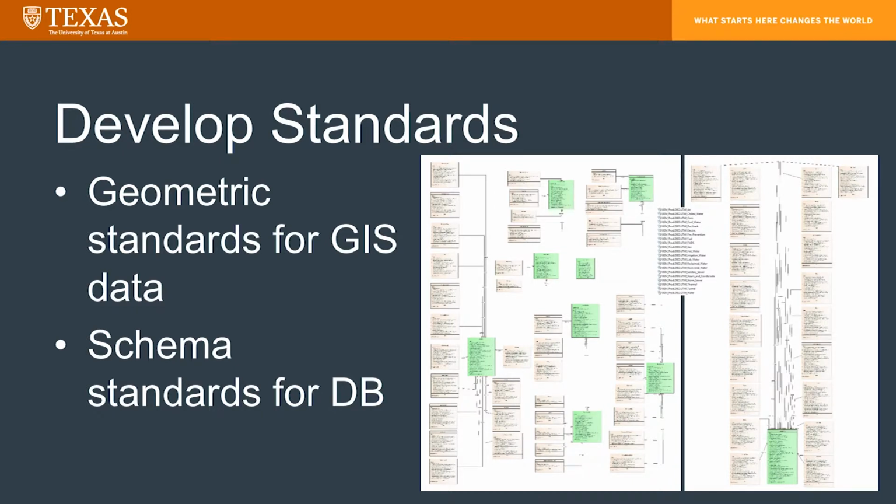Are your polylines going to break on nodes? And what I mean by nodes, those are going to be like gate valves and manholes and junction boxes, different things like that. Are your polylines going to break on those objects, or are they just going to be continuous through them? Are they going to break at intersections? These are types of things that you're going to be able to clean up as you're going through and separating out all this data, because that is what it is now at this point, is data.